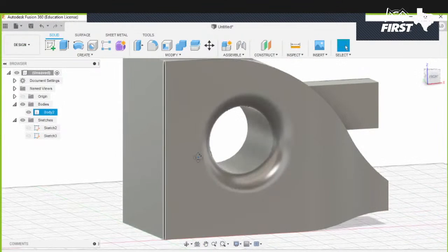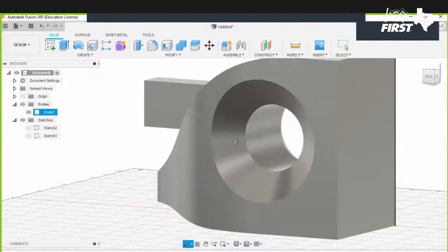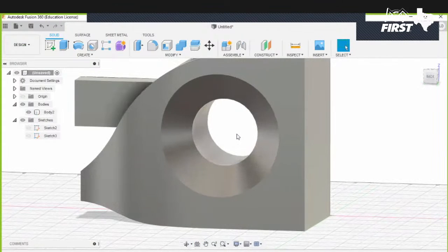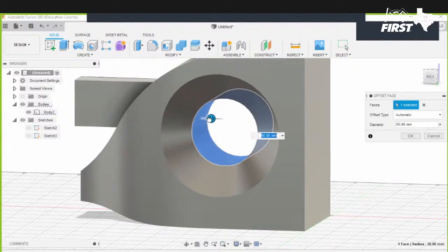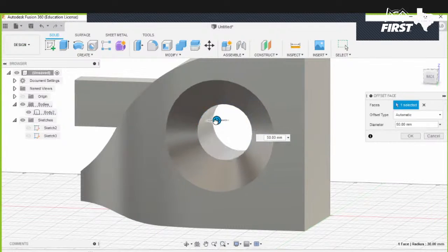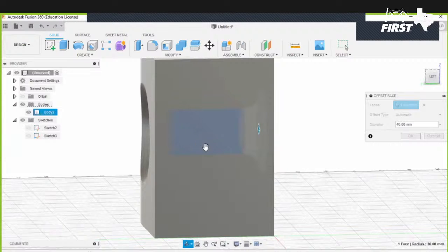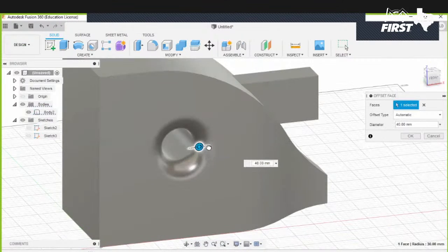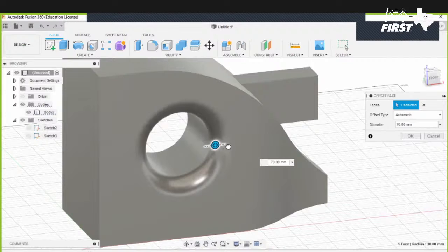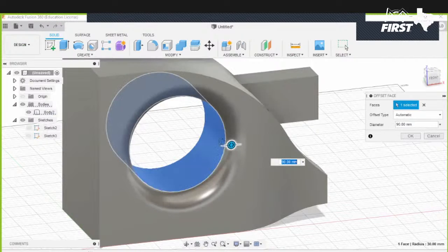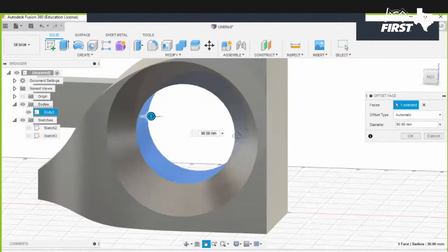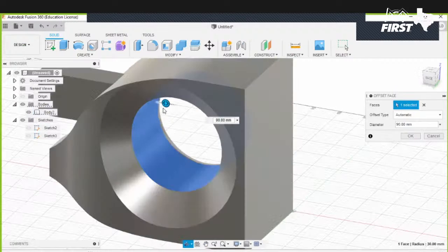And now the next question is, I said the press pull. The way we can implement this is we can maybe expand it or shrink it. Let's go to press pull. I can click this button here, and I can change the actual diameter. Notice when I pull it in, it shrinks. Right, notice the other side, it shrinks. But notice what's not changing. If you notice, the fillet is not changing, nor is the chamfer changing. All that's changing is the diameter.